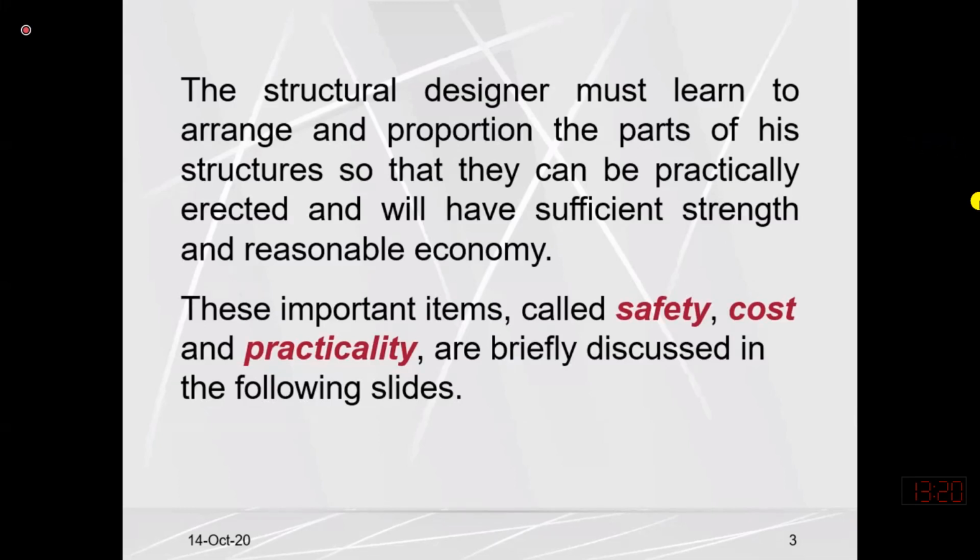But if we are using a very large length of the tension member, it can vibrate if it is not subjected to the load. Just like you can see with the wires of an electric pole. If they are not loaded, maybe there is sagging and the wire can vibrate due to the wind load. So it means that the length should be restricted to a certain limit.